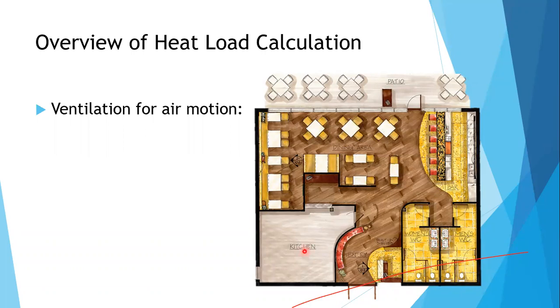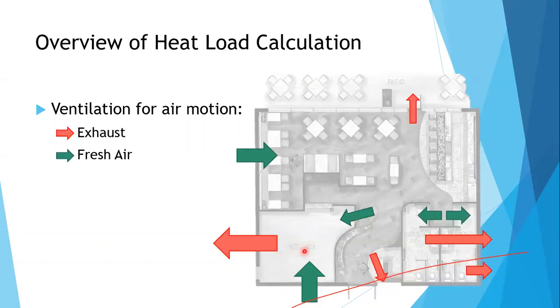Okay. All right. So how do we do that? What we do is we map out the direction to which the air will pass through. So example, kitchen, we exhaust out 100 cubic meter per hour. Again, these are assumed values. These are not calculated values. Assuming that the kitchen requires 100 cubic meter per hour, so you put in a fresh air of 90. So you're exhausting out 100, but you're only putting in 90 from your fresh air.